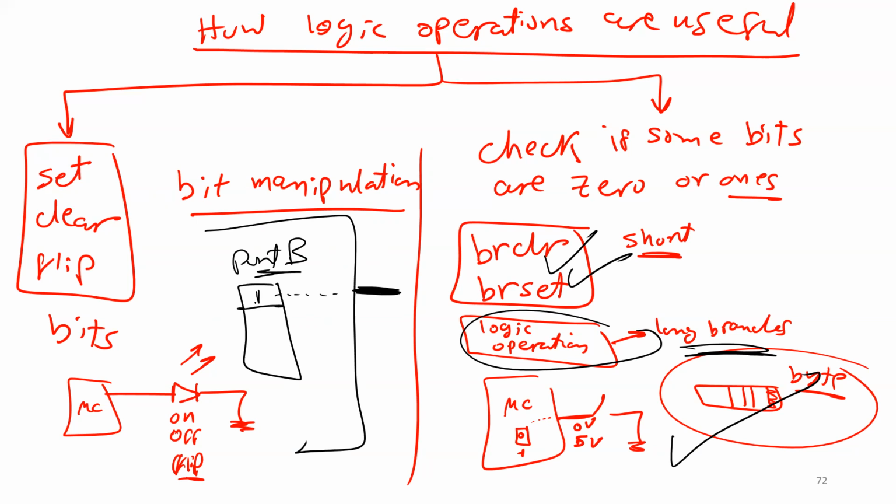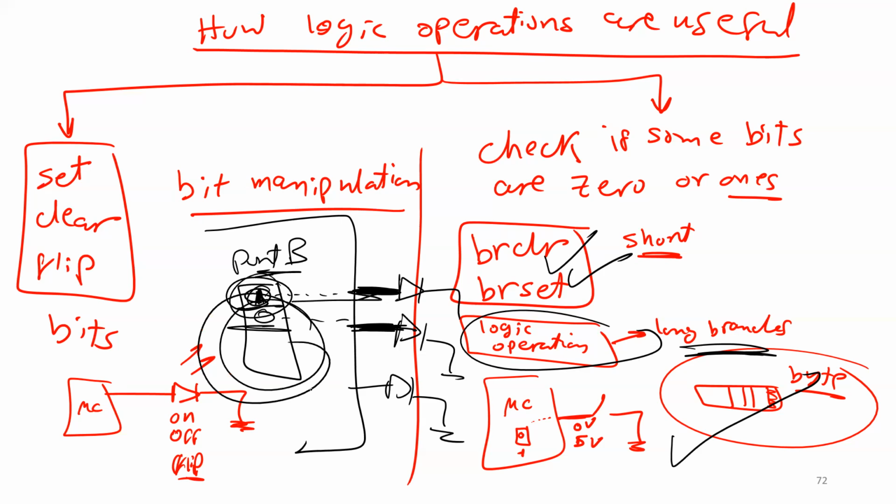When I put in the bit logic 1, the hardware is going to put here 5 volts. If I put in this bit 0, the hardware is going to put here 0 volt. You got what I'm saying? And then every pin here is connected to an LED. As you see here, we have 8 LEDs. So if I want to turn on one LED, I have to put 1 here in the corresponding bit to turn it on. If I want to turn it off, I have to put 0 here in this bit. For sure, I don't want to change the status of the other bits or the status of the other LEDs. So conclusion, make it easy.